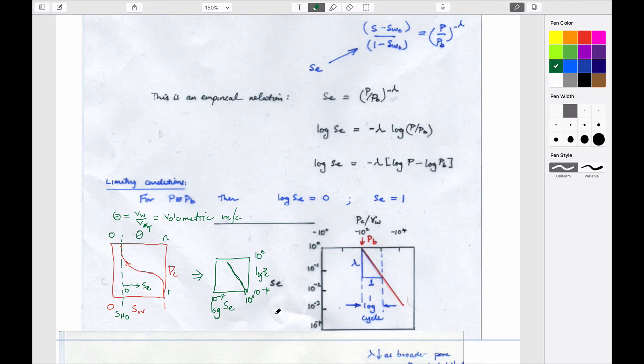And so where does this curve look? I think if you rotate this by 180 degrees, physically rotate it, not flip it, then you get this here. And that's what this is. So we can use our capillary pressure curves and relate them by a straight line relationship just by, one, plotting a different relationship in effective saturation, which the scale has changed from the irreducible saturation at 0 to 1, and then taking the log of that. Using the capillary pressure, and actually what it will usually be is the capillary pressure divided by unit weight of water, as we'll see in this.